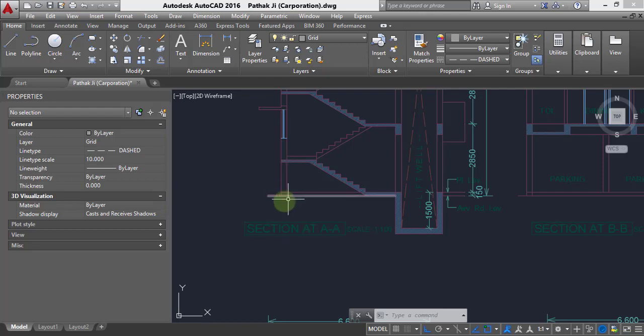Now, if you are not providing any plinth beam at this particular location, it will mean that the column height is going to be 2.1 plus this 2.85 meter. So the column length is going to be very large. You are going to have a very large unsupported length of the column, which is going to require more amount of steel, or the cross section size is going to increase.